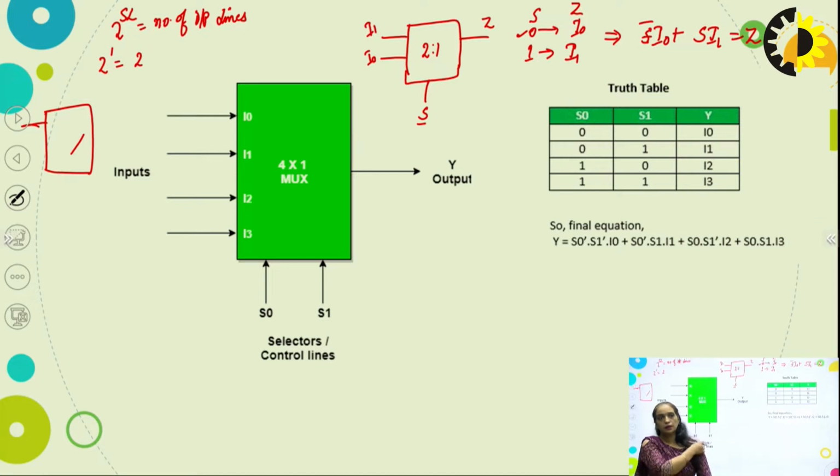Okay, so this is the simplest multiplexer circuit. We can also design it the other way around: if your selection line is 0, I want the I1 line to connect to the Z line, and when the selection line is 1, I want the data present at the I0 line to be connected to the output line. At a time, a single input line will be connected to the output line.